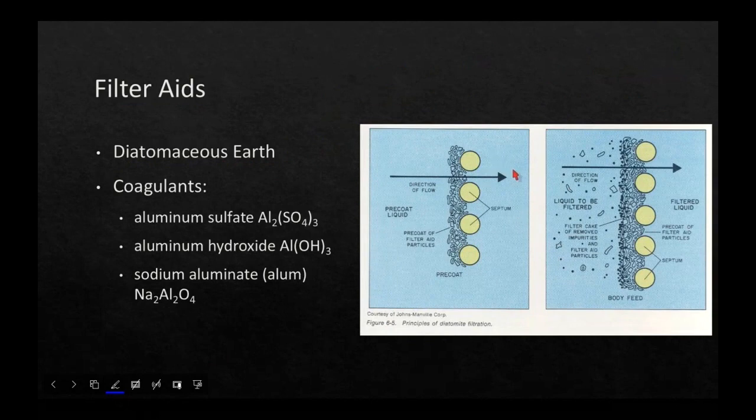Oh, look at this. This is the perfect slide. Imagine that there's a sock here, that nylon sock. And so we have all of these little diatom skeletons coating that filter. And so that's called our pre-coat. And then what we do is, along with the dirt, we're always adding additional diatoms.